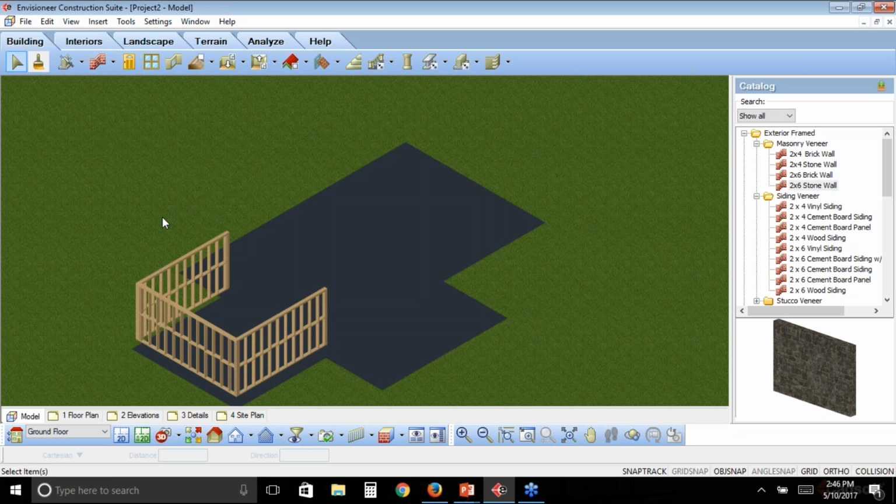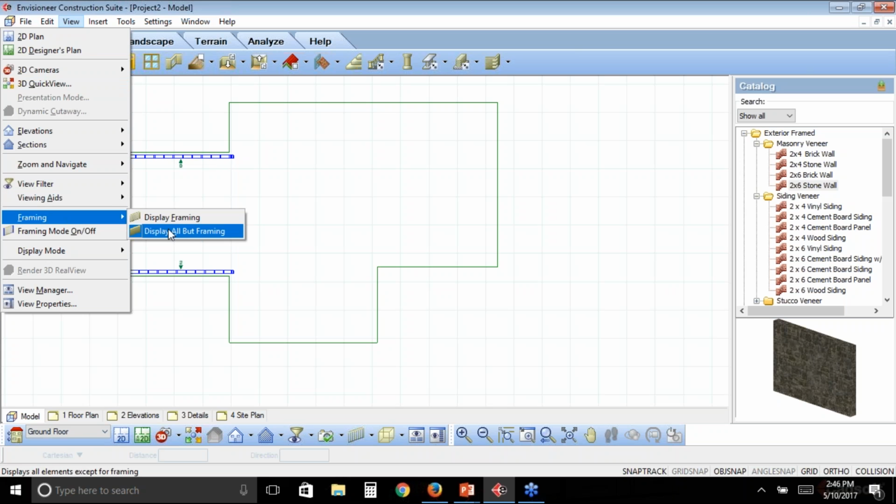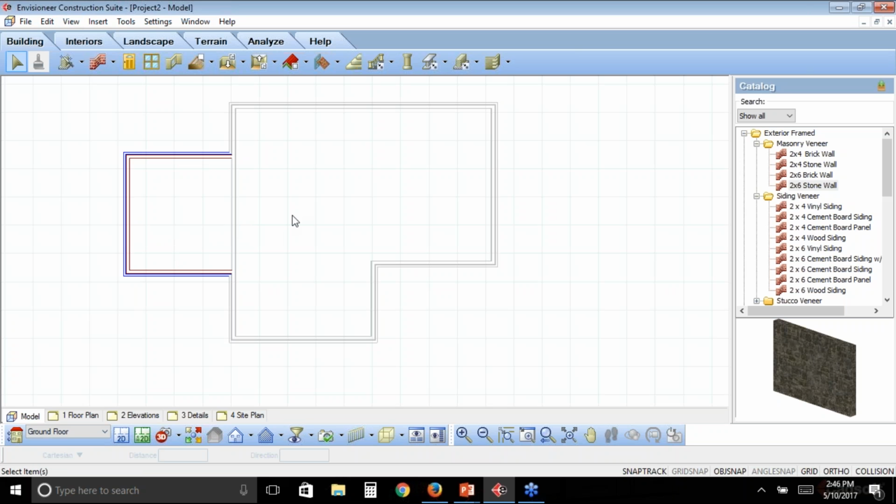And because my new construction is the only part that's going to frame, that's the only information that's going to quantify and be passed over to Buildertrend. So when we're looking at the model itself and choosing the elements from the catalog, you're going to have a distinction of new elements and existing elements, and those existing elements will not quantify, and they therefore will not pass over to Buildertrend.